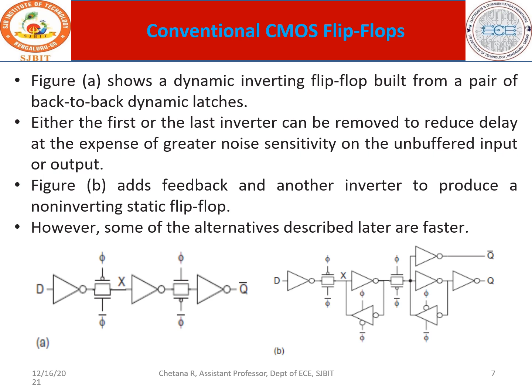So this in turn is nothing but a flip-flop which is built using dynamic latches. This thing is your dynamic latch, and when you combine them it gives rise to an inverting flip-flop. The output is Q bar, because there are three stages of inverters, and therefore the signal is inverting. If you had an even number, that is 1, 2, 3, 4, such inverters, you would have it as non-inverting.